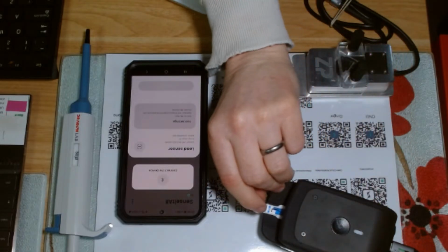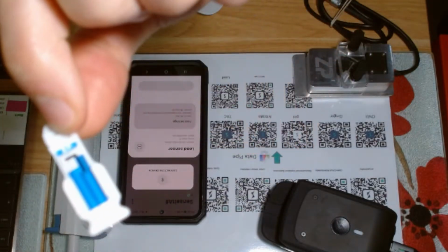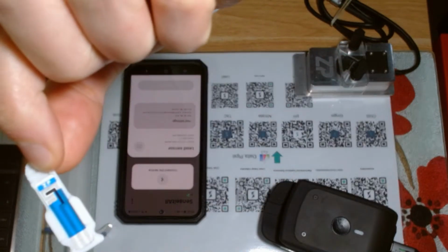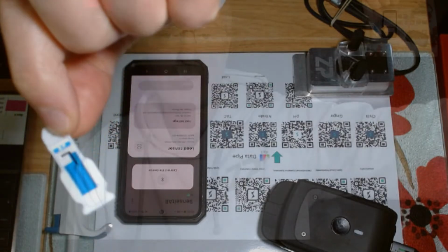The point is, with many biosensors, this is obviously a biosensor here, and I might actually go to this one here. The reference electrode is pretty close. You see that? You see I've got a black line in the middle. That's the working electrode. The reference electrode is this kind of silver line wrapped around the edges, and then there's a sort of rectangular electrode there as well. It's not the one that's wrapped around, but there's a rectangular. That's the counter electrode.